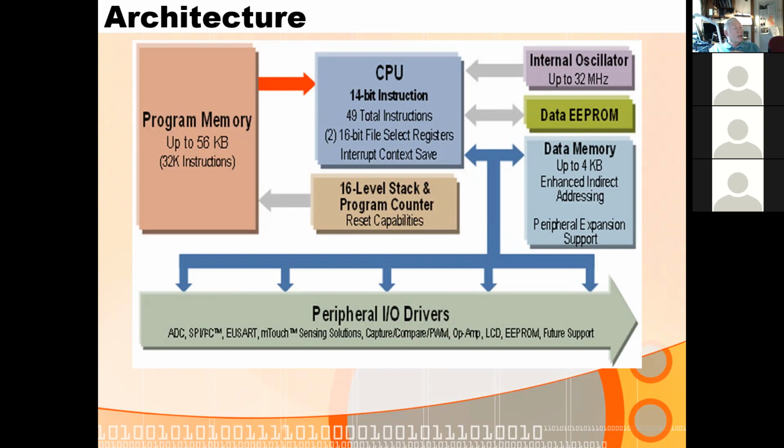In this chip, it has kind of a unique thing called a hardware stack. It has a dedicated area of 16, and I think there's 16-bit locations that make up its stack. And the program counter is also in this little area. And what happens is when you jump to a function and then you're going to jump back, the return address is pushed on this stack as a 15-bit value in one of the 16-bit registers. So you actually have an extra bit.